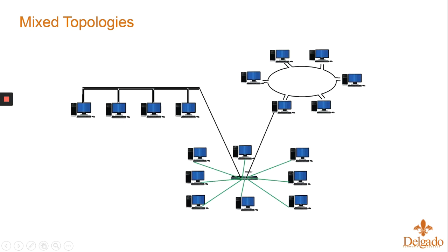So we can definitely mix and match our topologies, which is another reason why Ethernet has become a very popular network of choice for industrial automation and plant floors. In the past with serial networks, in addition to being limited in speed, distance, and number of devices, you also had the limitation of topology. It was either going to be a daisy chain type network or a trunk line type topology. Now we have the flexibility with Ethernet to mix and match topologies based on pieces of our plant.